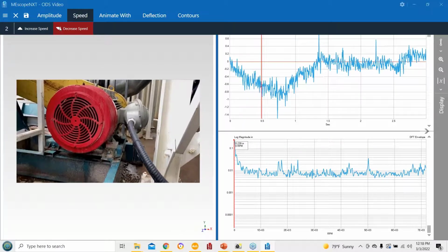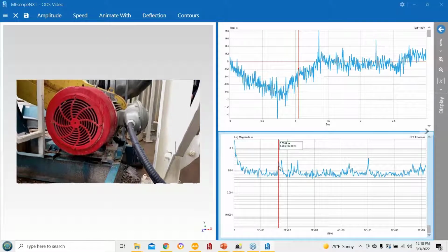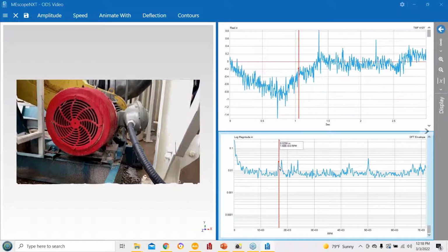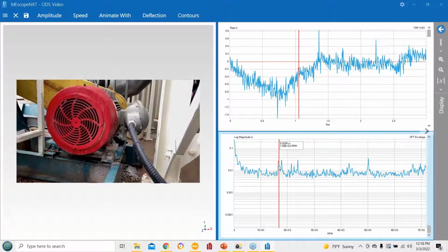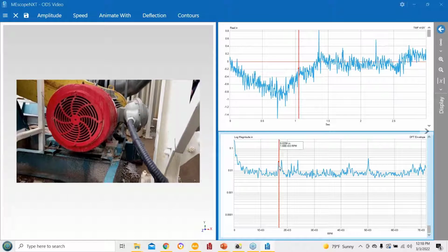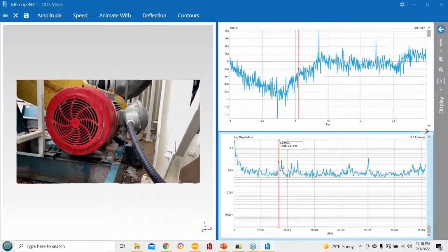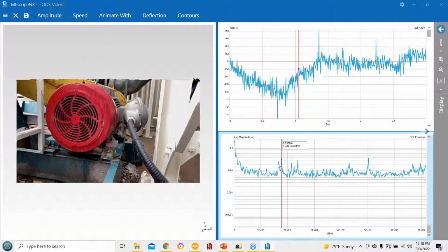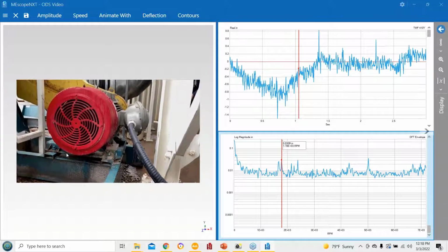When I do the FFT of this time waveform, I'm seeing these peaks, and this is an enveloped overlay, and there's a couple of peaks right here. And I think this one is, yeah, there we go. This is the one I was looking for, 1680, and I believe that's the speed of the motor. It's on a variable frequency drive. This is 1780, which actually this might be the motor. This might be a multiple of fan speed. But anyway, at 1780, I get a bouncing frequency.